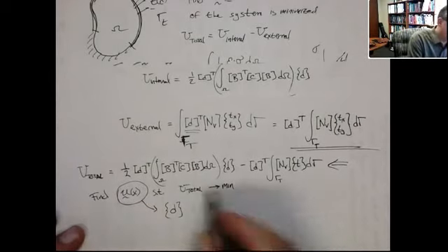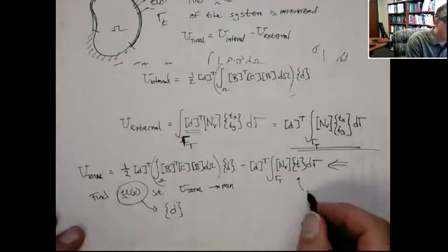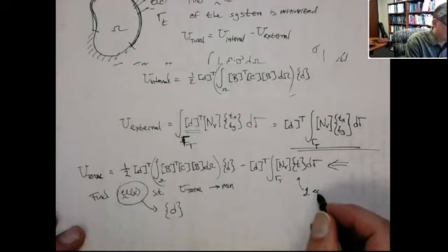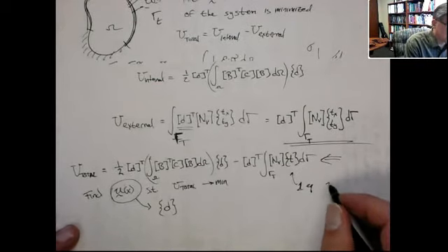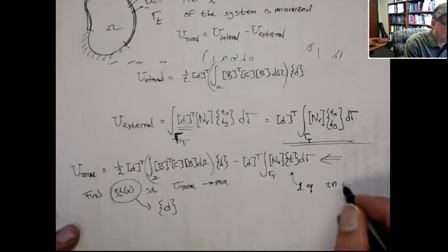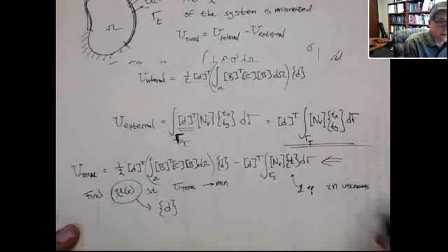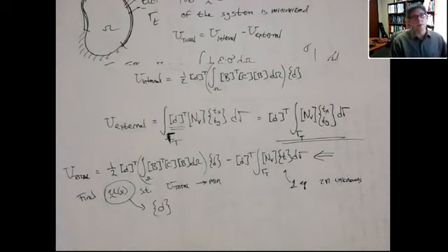This is one equation. If you look at this, this is a single equation with 2n unknowns, where n is the number of nodes, and you get 2 degrees of freedom for each node, so there's 2n unknowns. That's d, right? You get one equation. That doesn't do you any good.